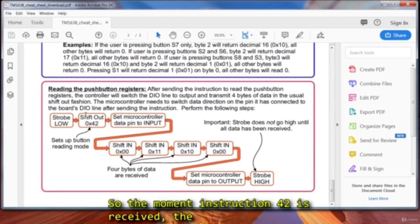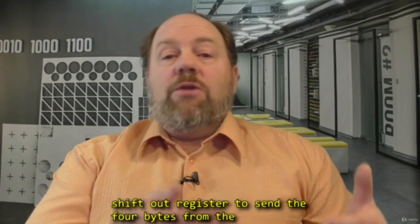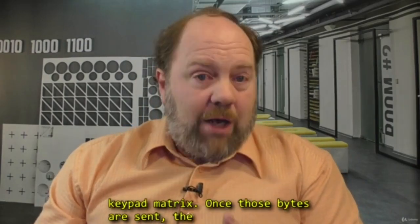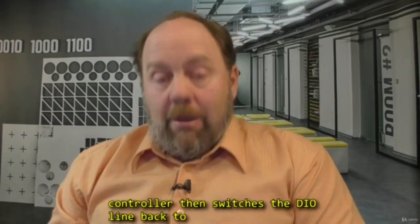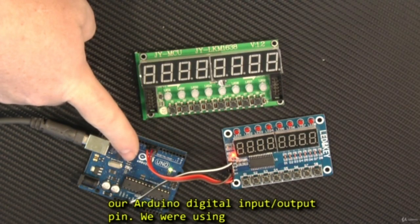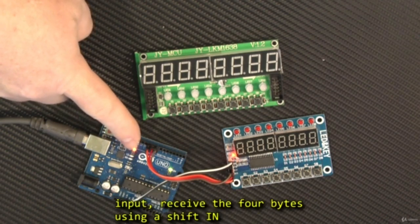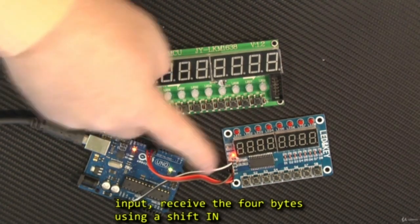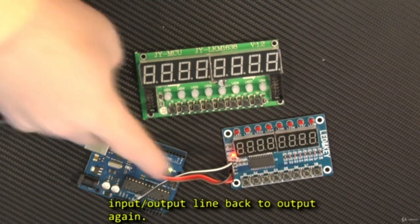So the moment the instruction 42 is received, the TM1638 switches the digital input-output line to output and uses a shift out register to send the 4 bytes from the keyboard matrix. Once those bytes are sent, the controller switches the DIO line back to input. Obviously, we have to switch modes on our Arduino digital input-output pin. We were using it as an output, so we have to switch from output to input, receive the 4 bytes using a shift in register, and then set the Arduino's digital input-output line back to output again.